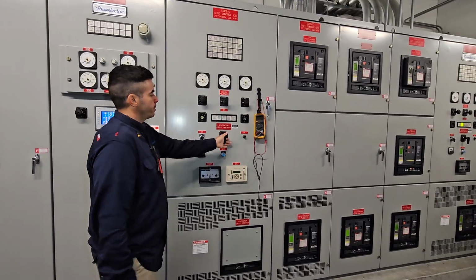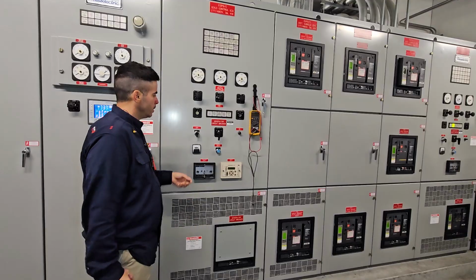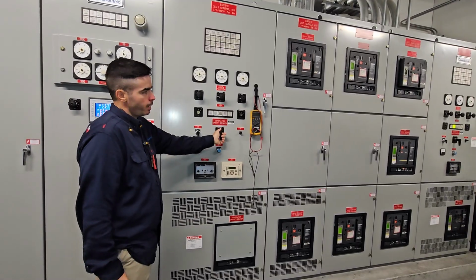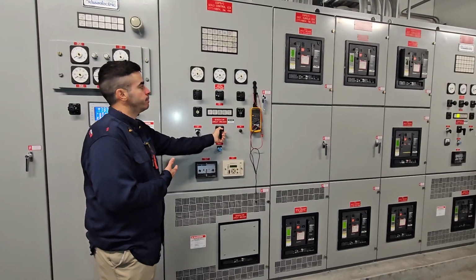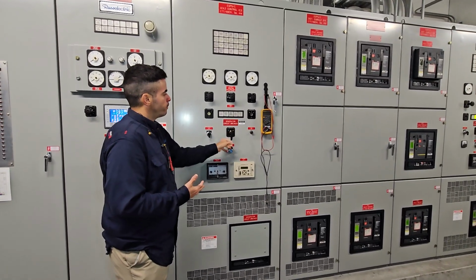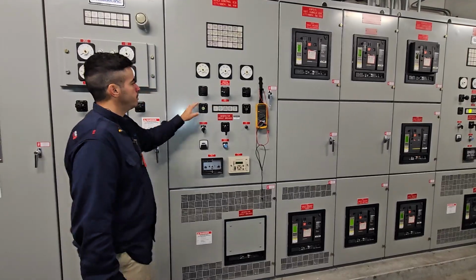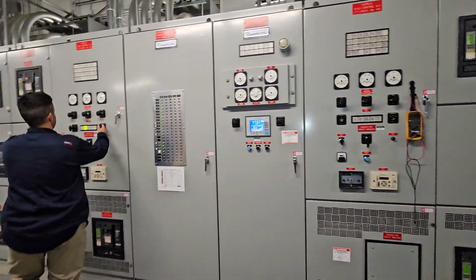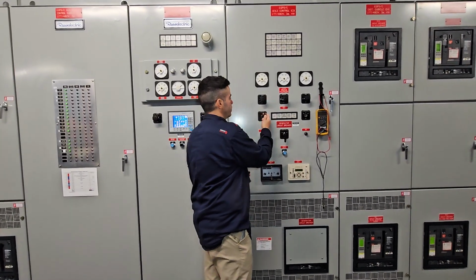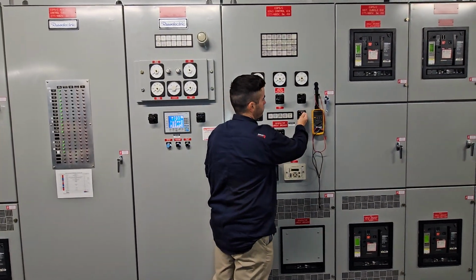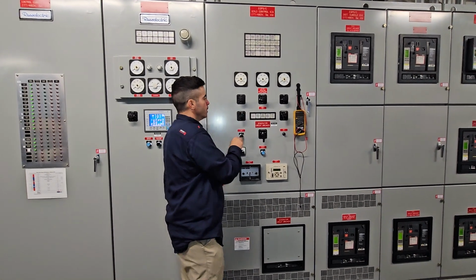And then we have the breaker close handle for close or open. This handle will allow you to close the breaker under a manual operation scenario. To do that, you have to turn on the synchroscope. We have two keys. It's actually one set of keys, because if I try to put this one here, it won't fit. It's only for the frequency meter switch, and then another one for the synchroscope switch.